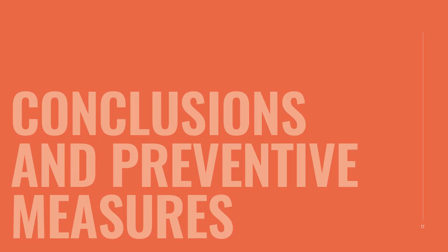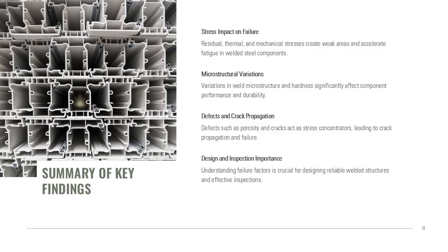Summary of key findings, preventive strategies, and best practices. Failure analysis of welded constructional steel components reveals that stresses, microstructural variations, and defects are primary contributors to failure. Residual and thermal stresses create weak zones, while mechanical stresses accelerate fatigue.